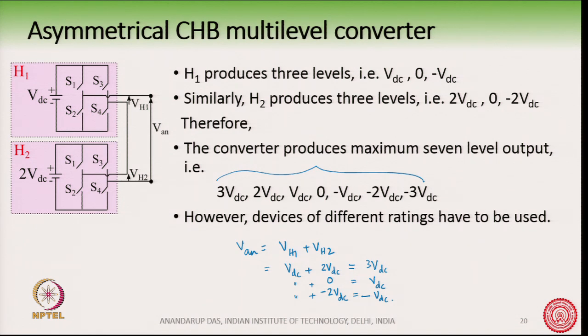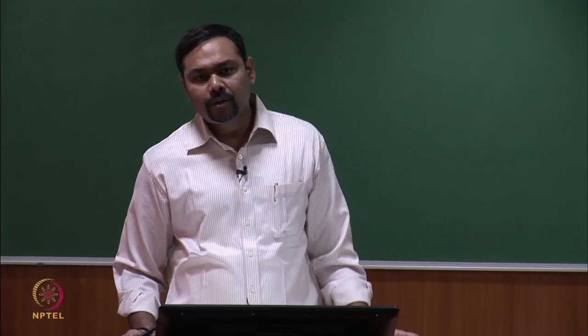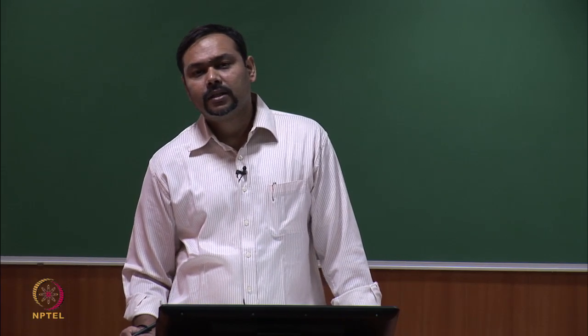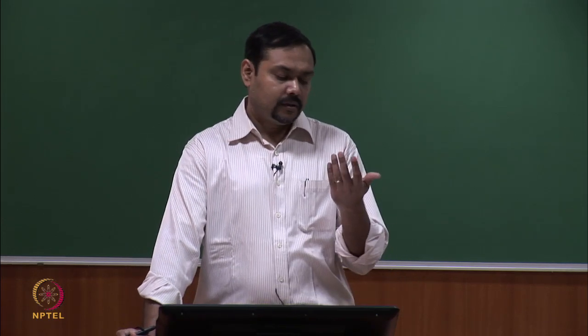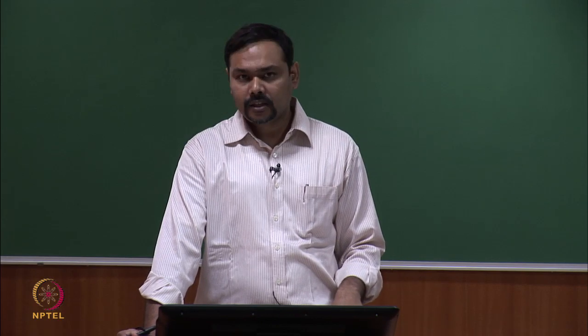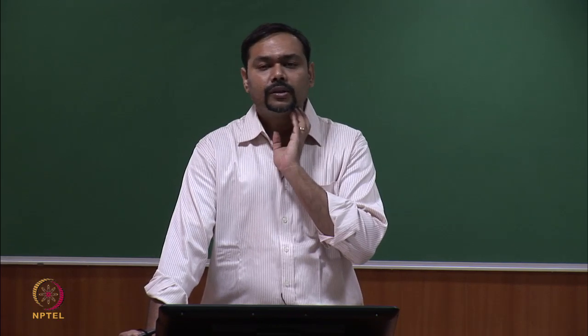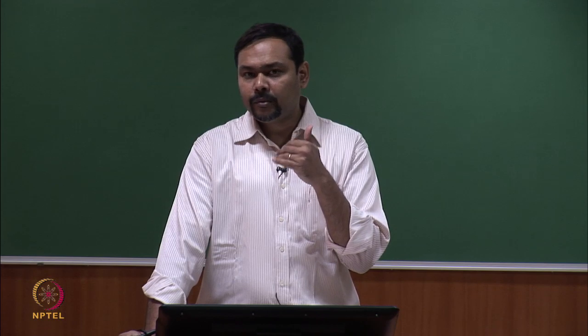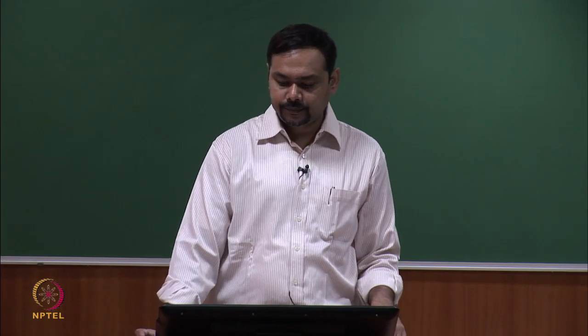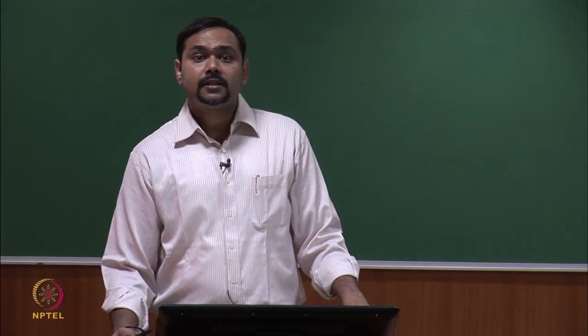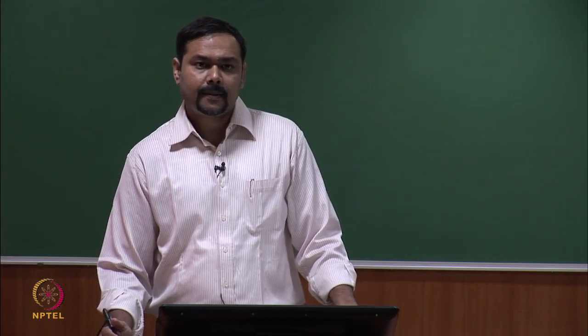So, it seems to be attractive with such an asymmetrical CHB, because now we are producing more levels, and from earlier discussion we can conclude that if the levels are more, then we will probably be going closer and closer to the ideal sine wave. So, this seems to be an attractive solution.